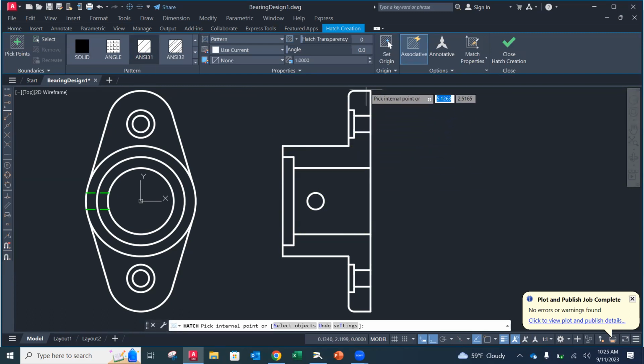And then all I'm going to do is hover. I haven't clicked anything. I'm going to hover and I'm going to look. It gives me a nice preview. Like, does that look okay? Is that proportional? And it looks good to me. But let's say I don't really like it. It seems like the lines are too far or too close together. This number right here, this is a symbol in front of it. This is to scale that. So let's say I want to do half scale, because right now it's 1:1. If I do 0.5 and I go back where I was, notice how they're a lot closer now. That's too close. I just want to show you that you can change that. I'm going to go back to 1 right here. And that looks better.